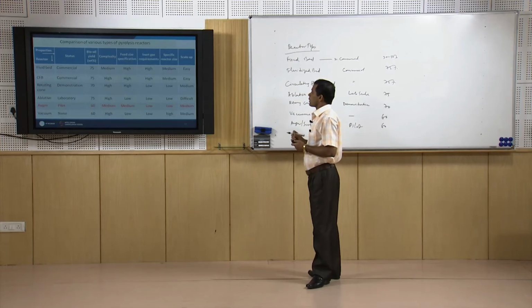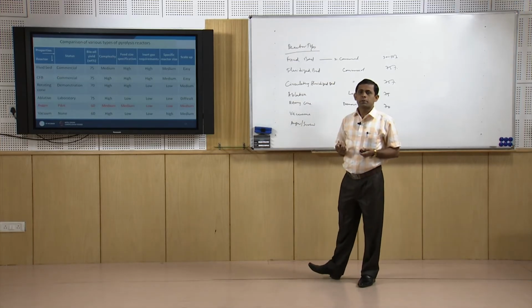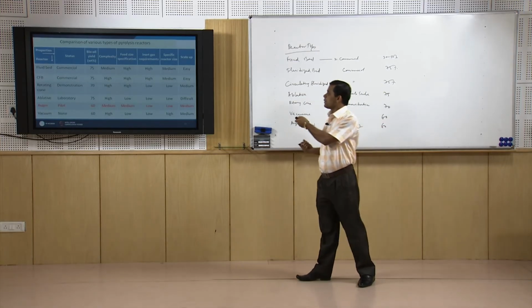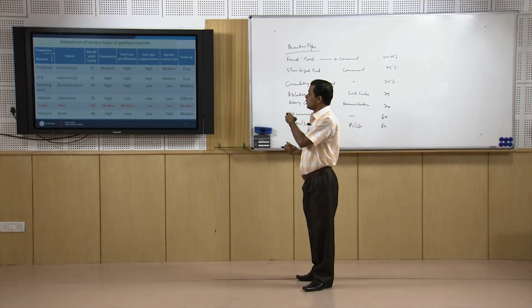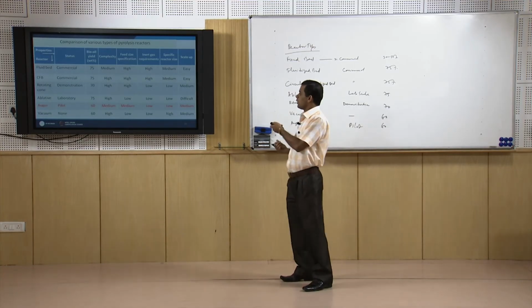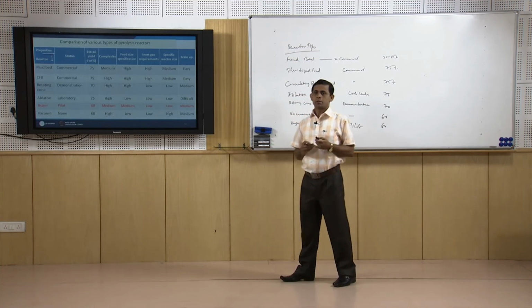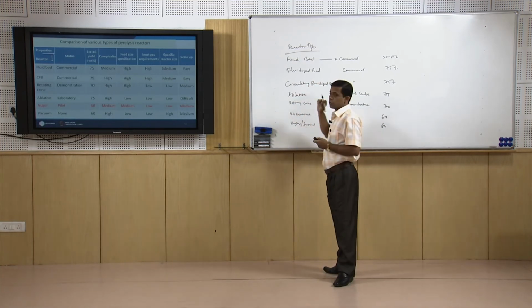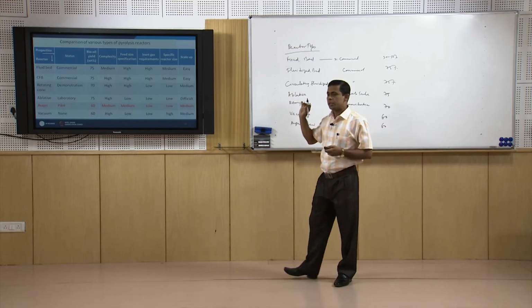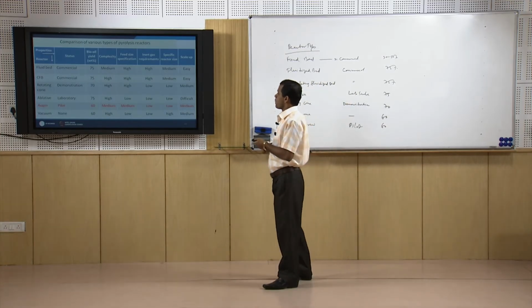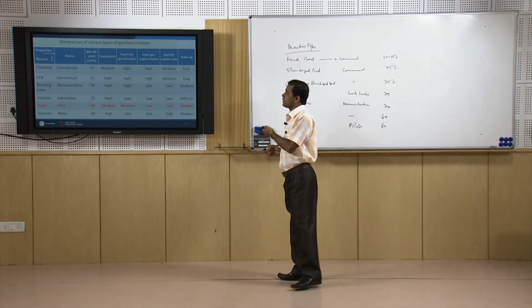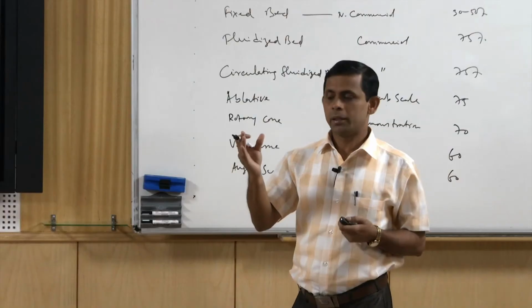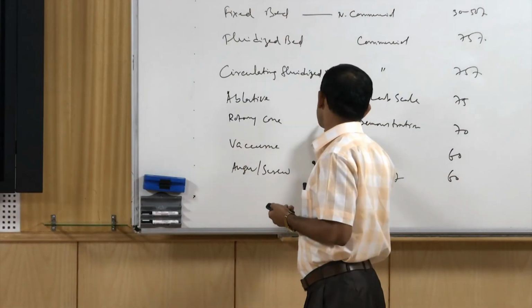If we think about ease of scale up, then obviously fluidized bed is easy to scale up, CFB is easy to scale up, but ablative is very difficult, and auger is medium. Screw reactors are also not so easy to scale up, but it is medium, it can be done. For feed size specification, fluidized bed is highly specific, the particle size should be less than 2 millimeter.